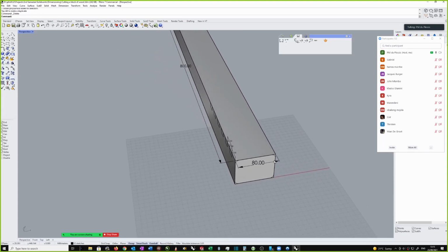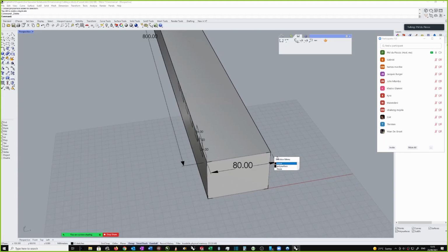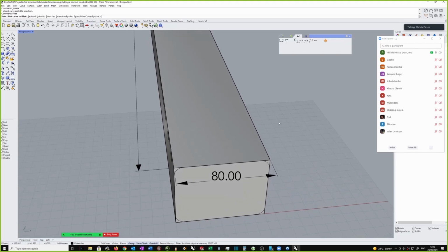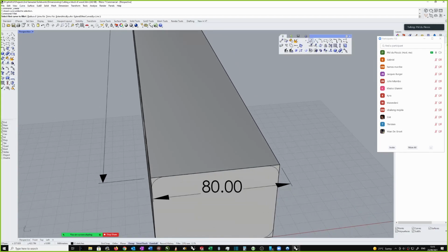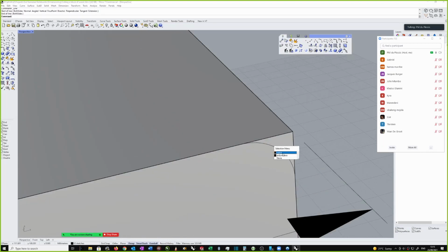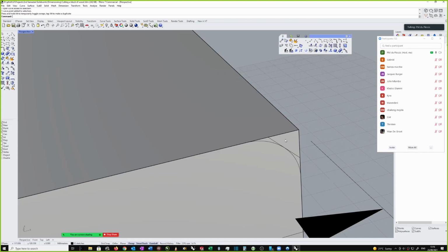And now I want to put fillets on it. These are 8 millimeter fillets. I haven't actually dimensioned it, but I should be able to just fillet it quickly. You'd maybe mark a line. This is probably what you do in the workshop. You'd probably find that point there and chop off a slice like that, and then you would curve the rest, like sand the rest around.